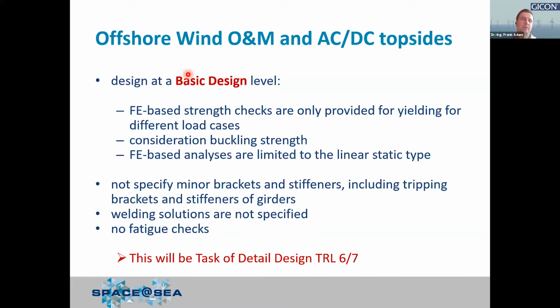The complete set of ultimate limit state loads was calculated to determine the resistance of the topside and to design it so that we are working on a safe level, also considering fatigue loading by increasing the loading from the ULS side in a specific way. So this design can be seen as a front-end engineering design, to go forward with a detailed design phase at a later stage in a later project.